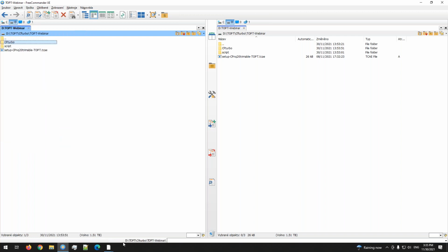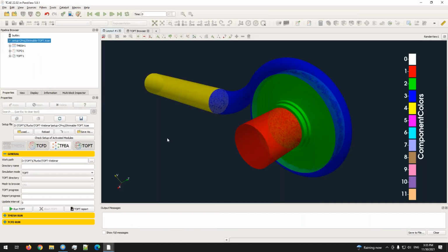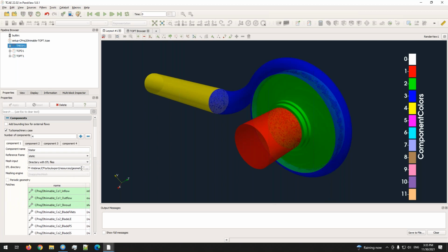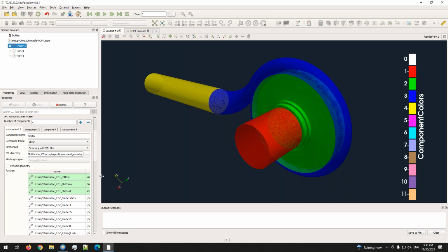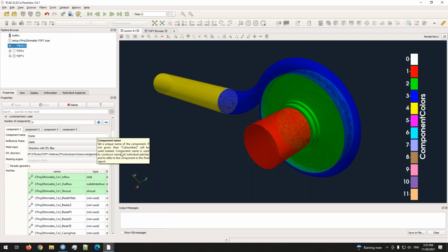Yeah, so if I go to my TOpt, which is here, basically in the tmesh we can see that the path remains the same. So we are in the CFturbo export resources geometry. Anytime the STLs are available, and for each run CFturbo gives us the new STLs for the new variants, and it can automatically be loaded. So we do not somehow adjust the path to the STLs. We did it in this way.